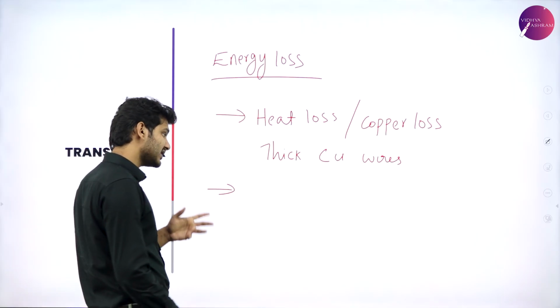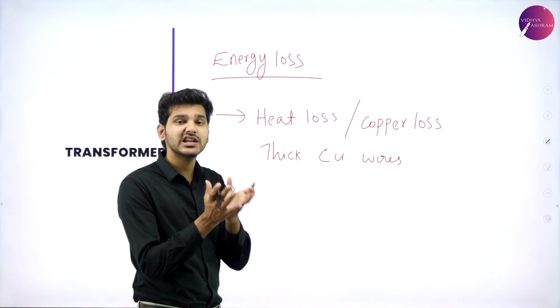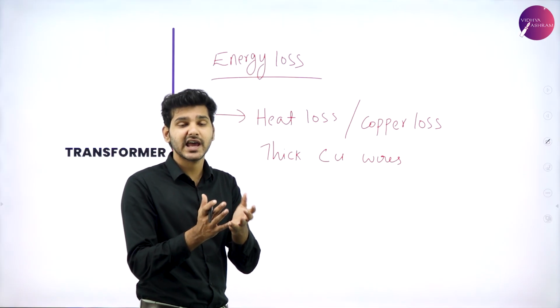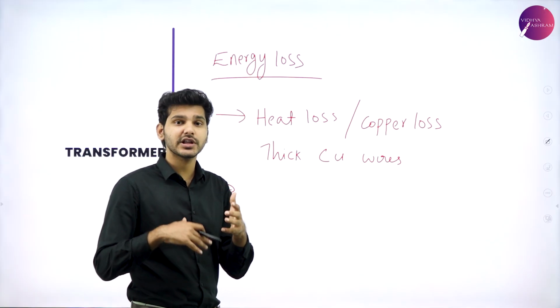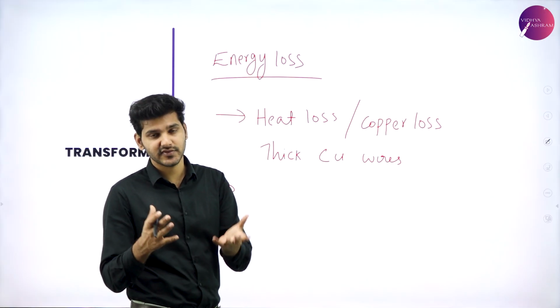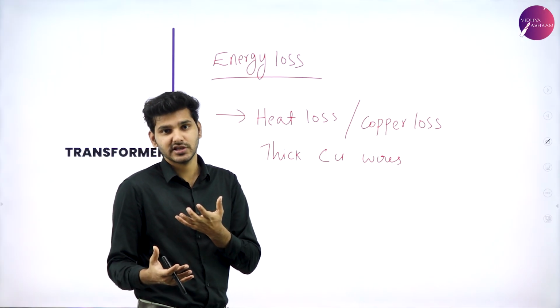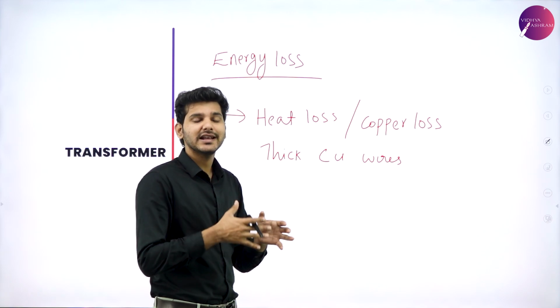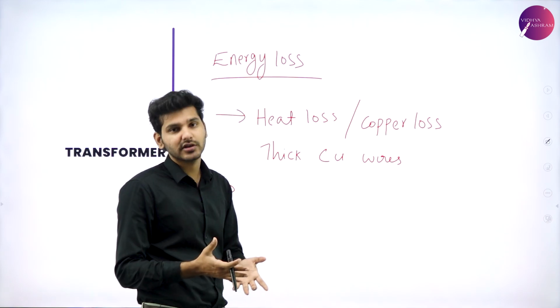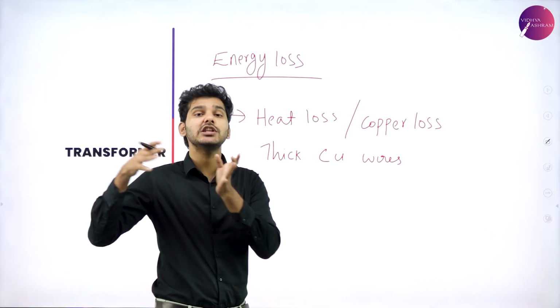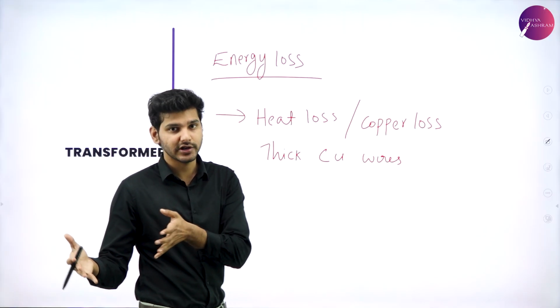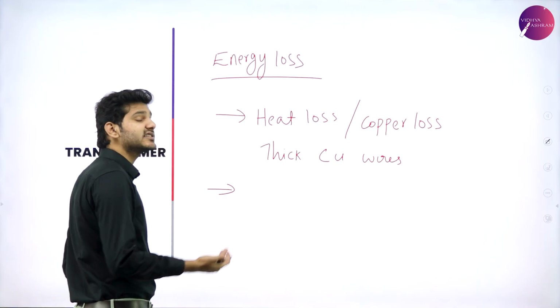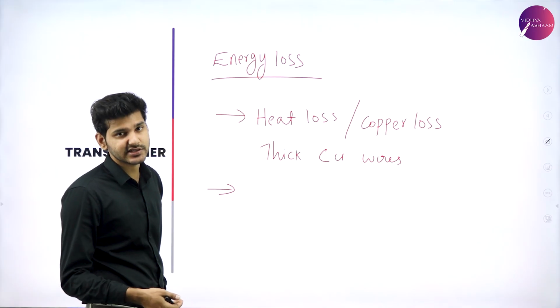So the magnetic flux in that coil can actually leak out. That leakage of flux causes efficiency loss. If the entire flux is not contained within the coil, it cannot efficiently induce EMF in the secondary coil, so efficiency will decrease.